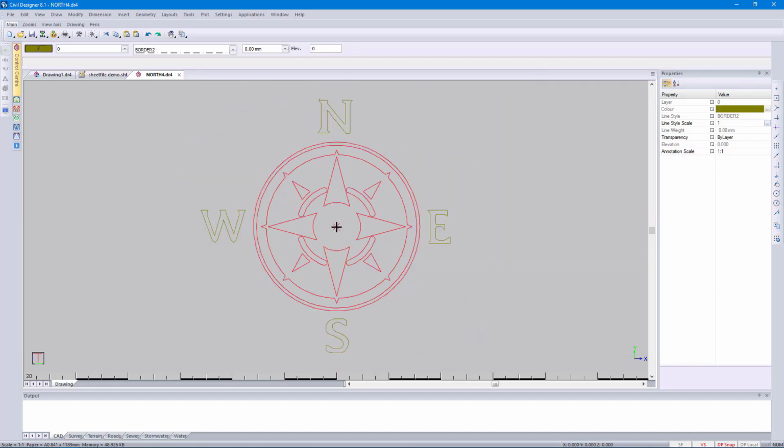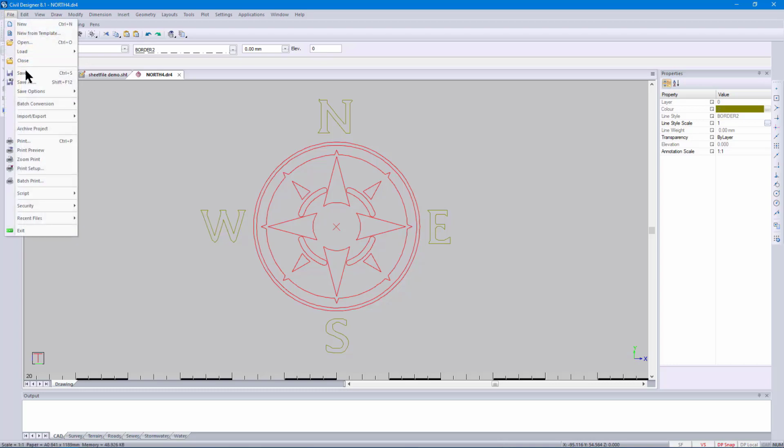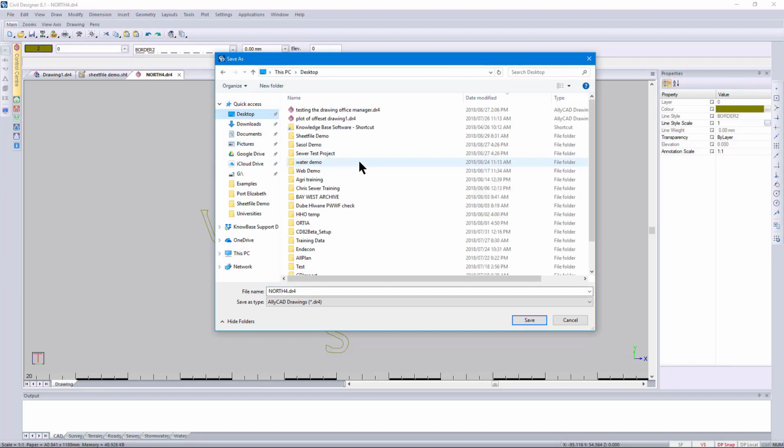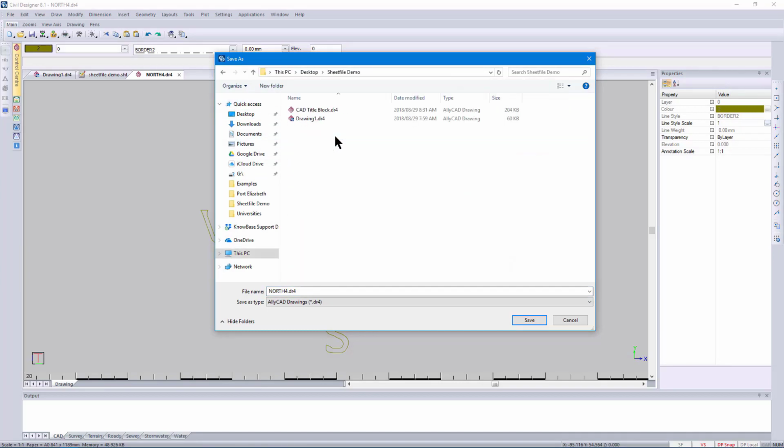And I would like to take it off the server and onto my location where I'm saving my project, so that the north side symbol becomes part of this project, so that if anything gets updated, my project symbol stays the same. You'll see that it's CAD entities. It doesn't need a block, but the center pivot point needs to be coordinates 0, 0.